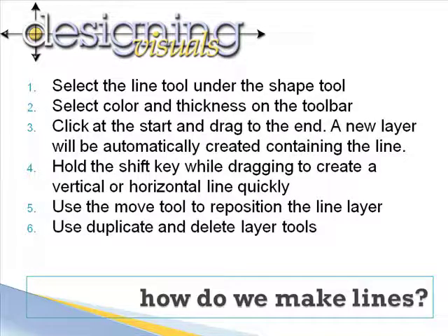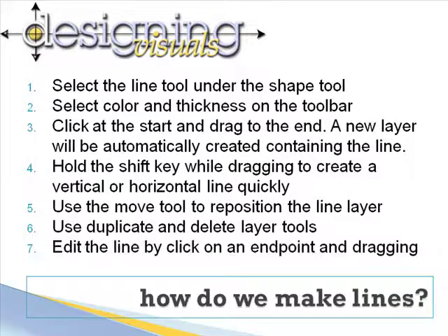Duplicate and delete the layers as you see fit. Probably you'll find it just as fast to draw a line as to duplicate the layer, but that's an option for you as well. You edit a line by simply clicking on one of the endpoints of the line, the beginning or the end, and dragging that endpoint to a new location.